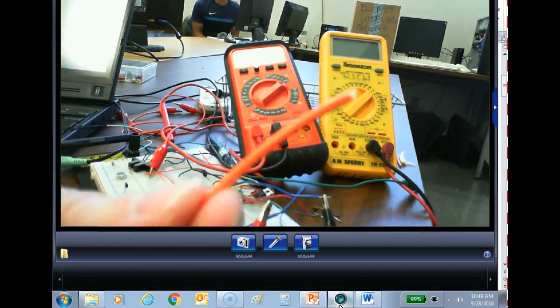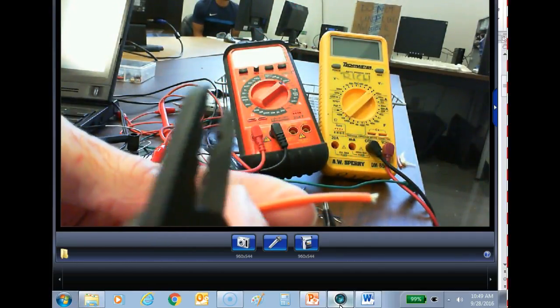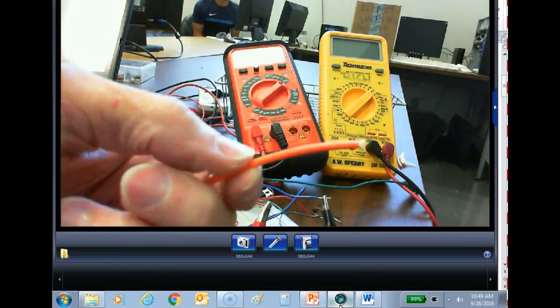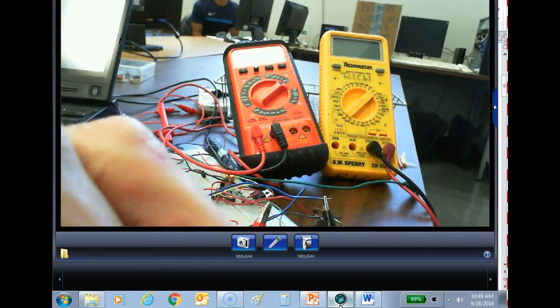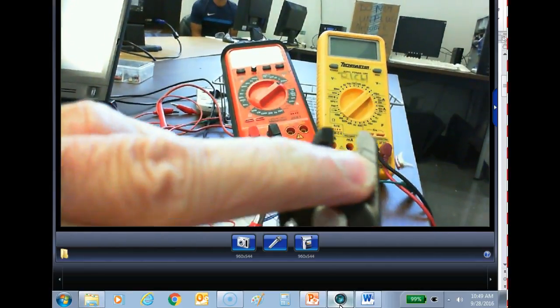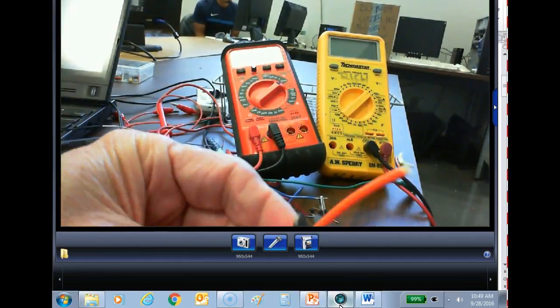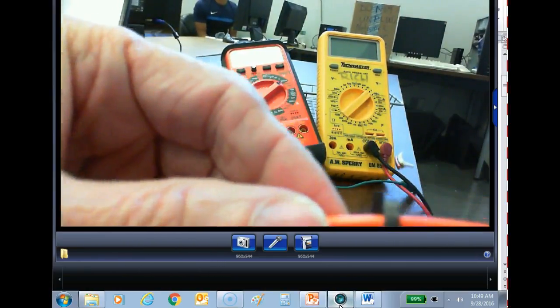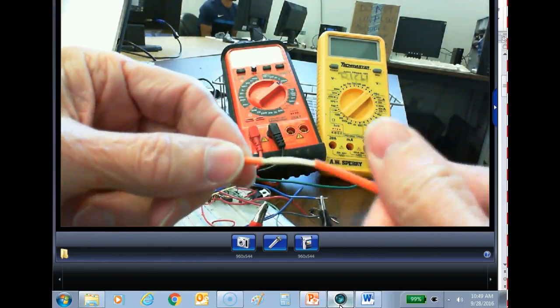First of all, this is what you'll get right here. And the first thing you're going to do is mark your outside jacket. You're going to take the outside of the 3-hole strippers right here. You're just going to close it. You're not going to twist or do anything else. You're just going to close it. Then you're going to grab this and twist it and pull it off.